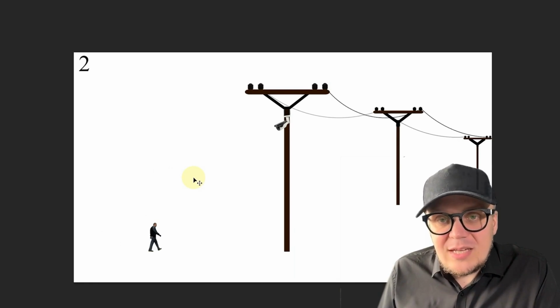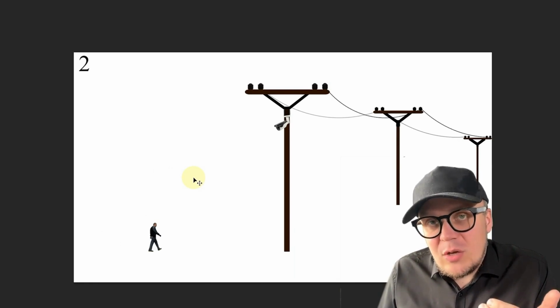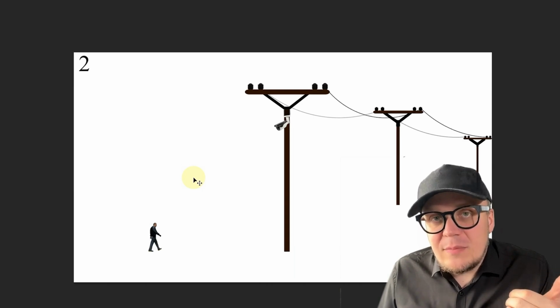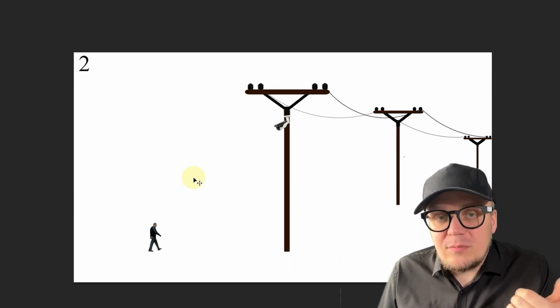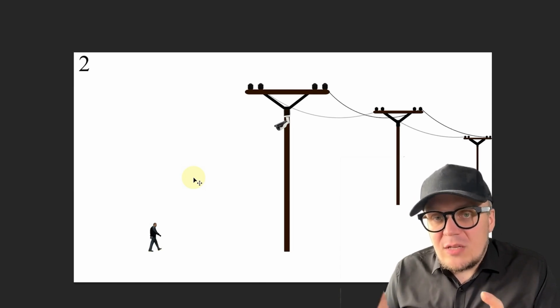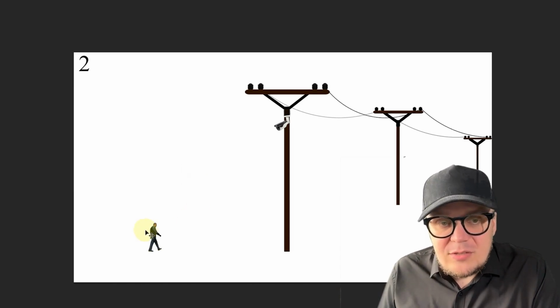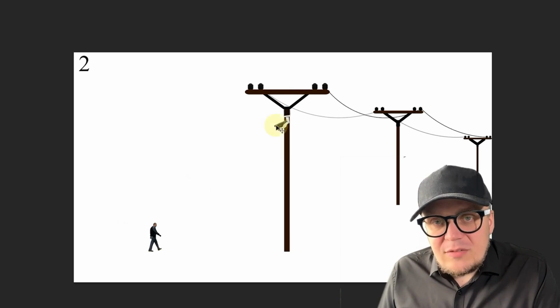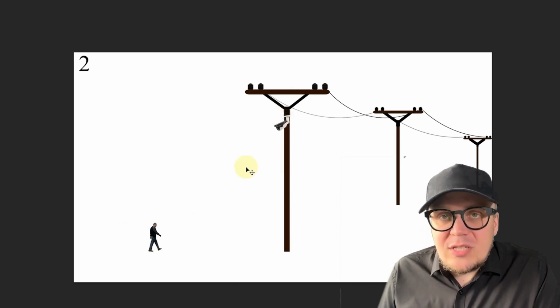Such a surveillance camera can also be installed, but it should be an additional camera, not the main one. That is, there is surveillance for security, whose task is, accordingly, to capture faces and car license plates. There is surveillance for comfort. For comfort, such a camera can be installed to additionally see your entire area at once. The same applies when a car passes by here if the camera is mounted too high. This will also make it difficult for you to read the license plate.